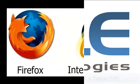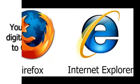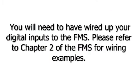All RLE web-based equipment can be configured using Firefox or Internet Explorer for a web browser. Getting started, you should have already wired up the digital inputs to the FMS. If you need to refer to any wiring examples, please refer to Chapter 2 of the FMS User Guide.